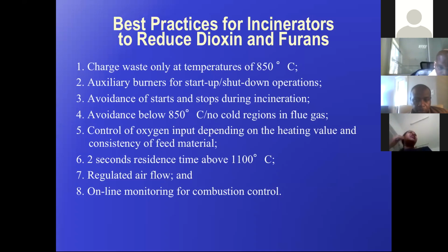Also, since there are different incinerators out there, with different designs, if you don't have the automated dual chamber incinerators, it's important to have your process established for the type of incinerators you have. I think another key ingredient to have full combustion here is to have good airflow. Even with the De Montfort, the brick constructed incinerator, it's a dual chamber incinerator, but there are no auxiliary fans. Once the incinerator is stoked up, there's a natural airflow that allows full combustion to take place.